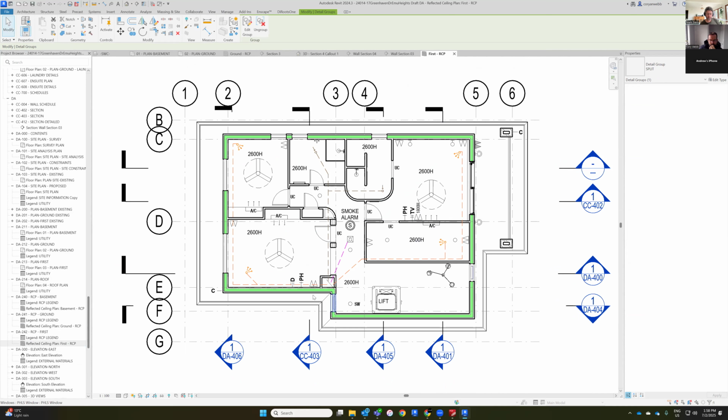And then the orange again, that's the HRV coming up from below with supply into the bedrooms, the orange ones, and then extraction from the ensuite and the bathroom. And then this is the dehumidification in the corridor here. I like your little arrow things. Oh, these bad boys.